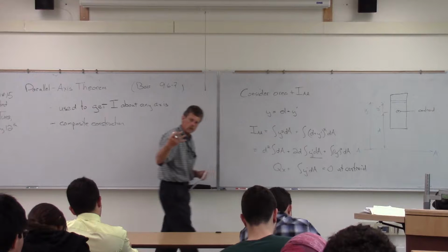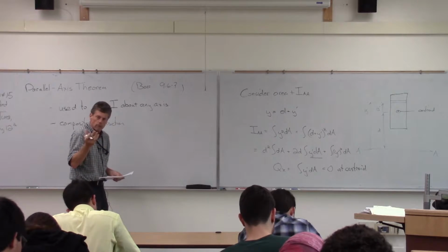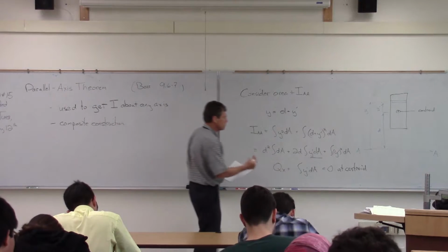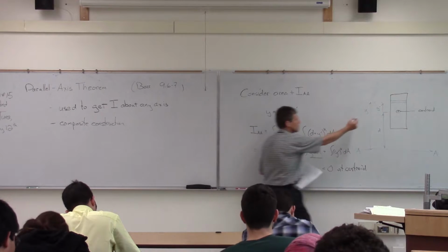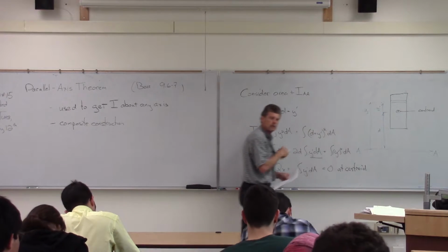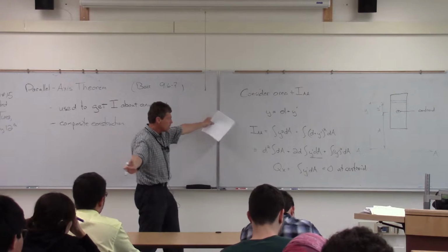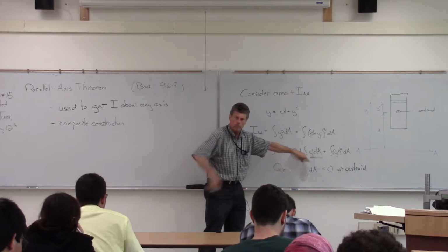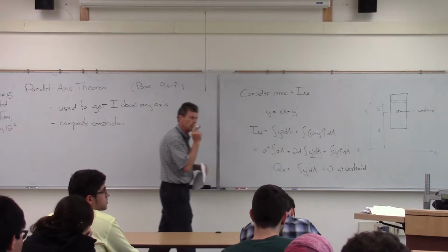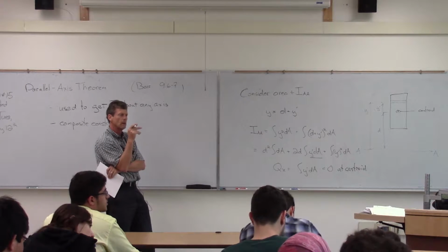The way we've laid this equation out, then, that term goes away because it's based at the centroid. It's measuring from this point here now, the centroid, and it's going to go up and down. Positive quantities and negative quantities, since there's only the linear term there, will cancel out. It's only if it's uniform density.